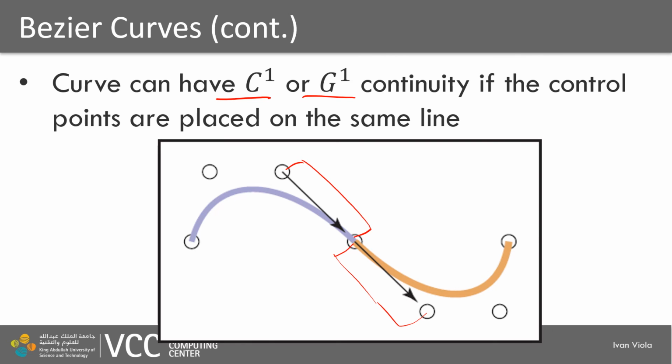And if they don't, but one is, let's say, a little bit longer, then we have the G1 continuity. As we see here, the position of the previous points next to the points which are forming the tangent will be defining the curvature. And if they are symmetrically placed, then there will also be continuity in the curvature.